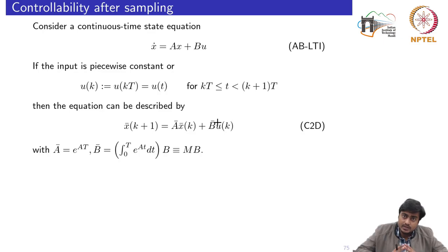If the discrete time system is already given to us, then we had studied different tests to carry out whether the system is controllable or whether the system is stabilizable. Now we had separate tests for the continuous time system also, but here the problem is, if I use the continuous to discrete transformation given a continuous time system, what can I comment on its controllability?